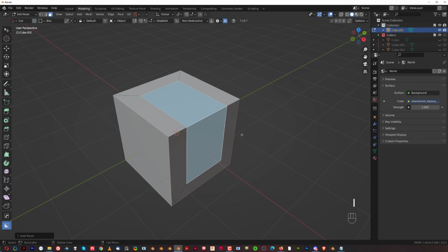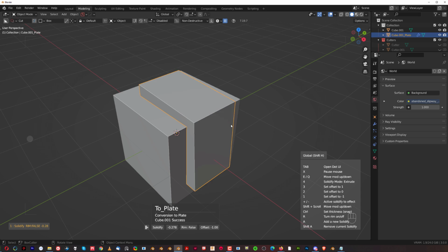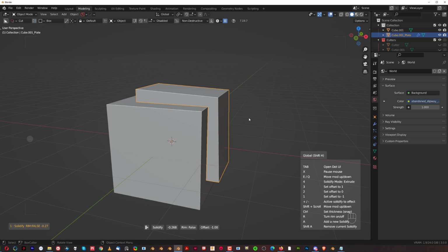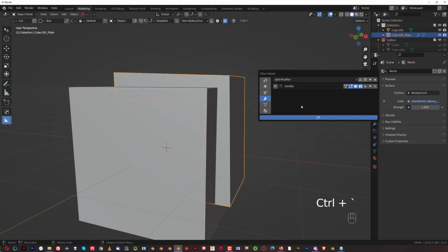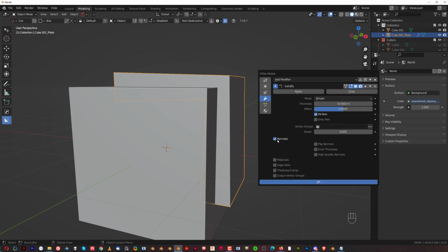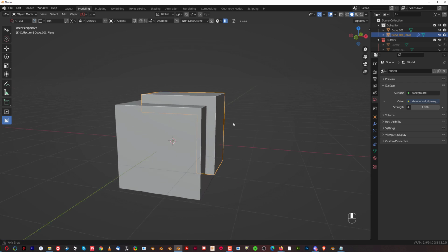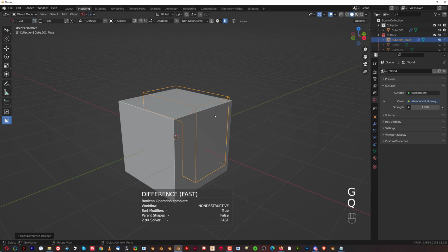When I scale this one and go to Q and Shift click on Curve Extract, I'm going to get this paneling effect. Now the cool thing about it is you can go both ways if I press 2, because it behaves like solidification. All you need to do to fix it is go to solidification and simply use normals and even thickness, which will fix this problem here. And there you go, you got a really interesting plating on top of this mesh.